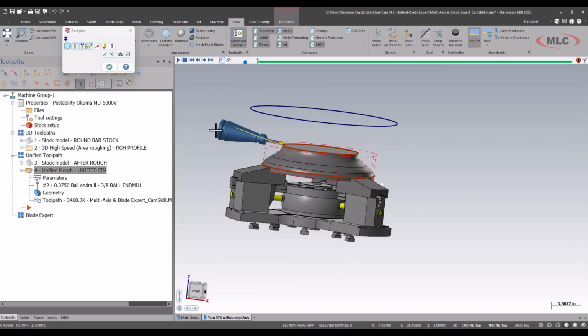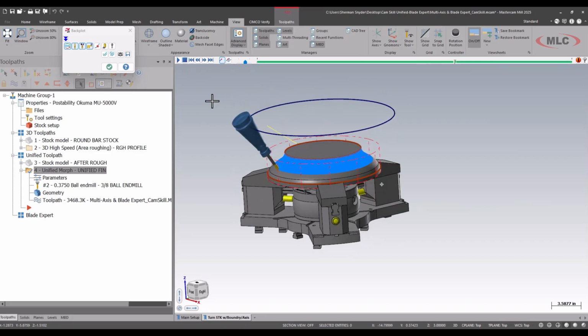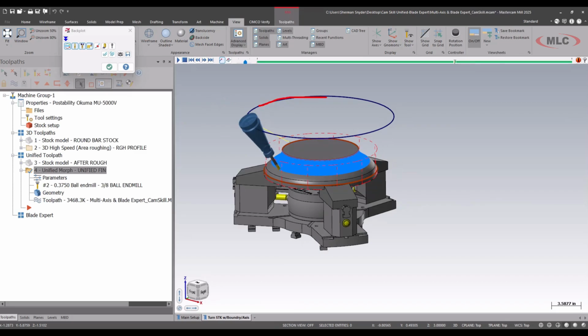And one thing I notice is that tool is tilting pretty major here. The last thing I want to do is have my table kick up like this towards my spindle. But as you can see, as we go around the part, the tool is following the surface. And I actually want to limit how much it's tilting. And being that we already have a boundary curve above, we'll go ahead and take advantage of this boundary curve that we use for our roughing operation.